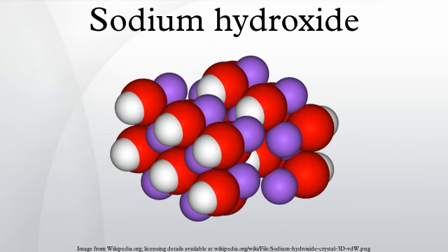Cleaning agent. Sodium hydroxide is frequently used as an industrial cleaning agent, where it is often called caustic. It is added to water, heated, and then used to clean process equipment, storage tanks, etc. It can dissolve grease, oils, fats and protein-based deposits.